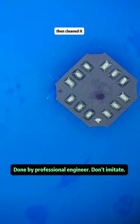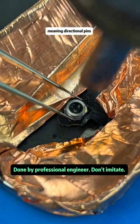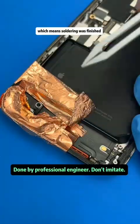Then cleaned it, and once again applied a small amount of flux to the solder pads on the flex cable. This barometric sensor has segmented pins, meaning directional pins. We aligned it, then used the heat gun to heat it until we could touch it and feel it become elastic, which means soldering was finished.